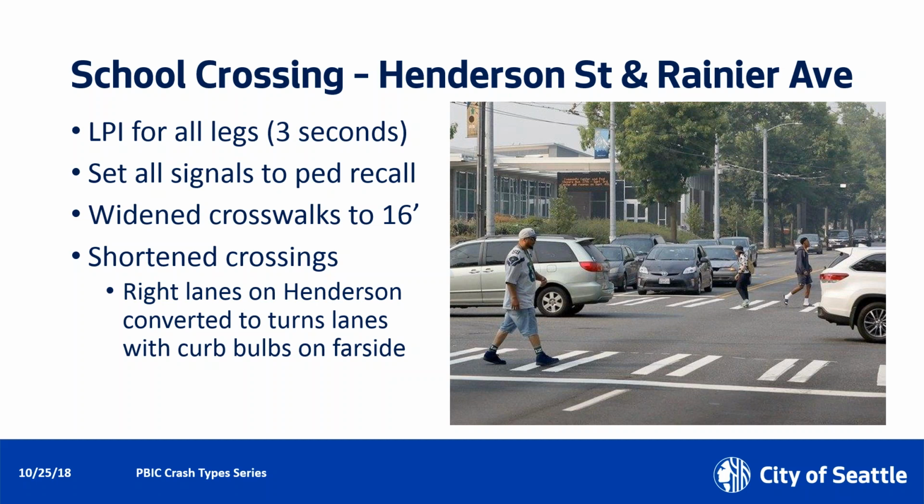There were elementary schools, middle schools, and high schools in this area. And anecdotally, we don't have any data, but we believe that students may be less likely to hit the pedestrian buttons. Based on a lot of national studies that I've looked at over the last 10 to 20 years, even for adults and the general population, the highest percentage of pedestrians to hit the push button is about 60%. You only see about 60% of pedestrians using push buttons that aren't set to recall. So putting them on recall brings up the pedestrian phase every time, which means they're also going to be getting that LPI every time as well.